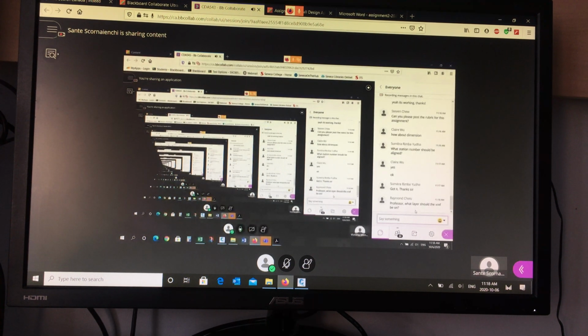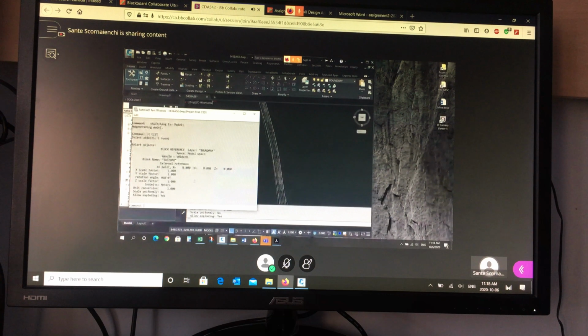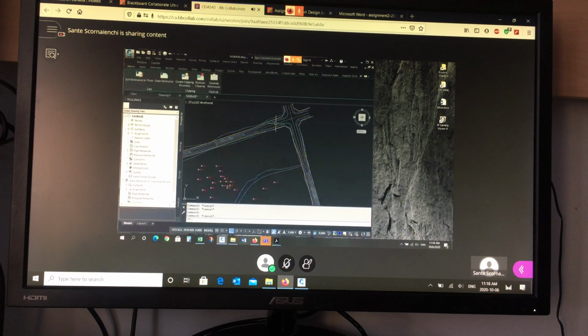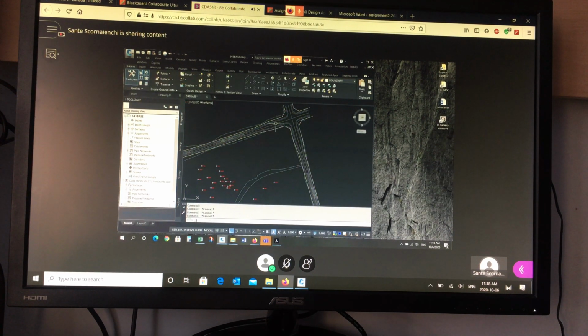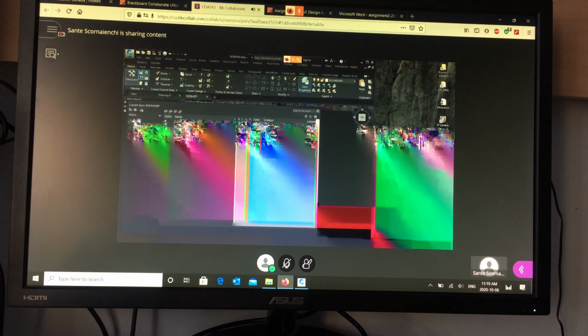The X-reference, when it comes in by default, typically, so if I list mine, you'll see it's on the current layer, boundary. It's probably a stupid layer to put it on. You could leave it on layer 0. You can create a layer, and normally I'm not going to be too picky with this, but I usually put it on a layer called XREF and then Topo.